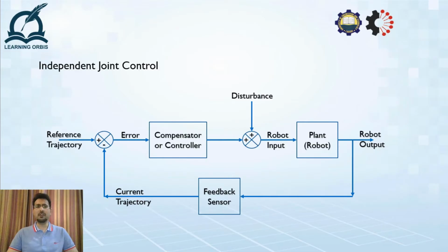Things get complicated when we factor in the robotic manipulator's physical structure. Remember that in the previous video, I explained that the dynamic equation of a robot is in fact a set of n coupled nonlinear second-order differential equations. Therefore, you should appreciate that if we have three connected links in a robotic manipulator, then if only one of them moves, the other two links will feel a change in overall inertia and gravitational forces, which will cause those links to move as well.